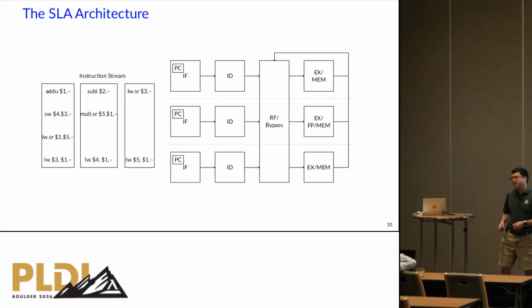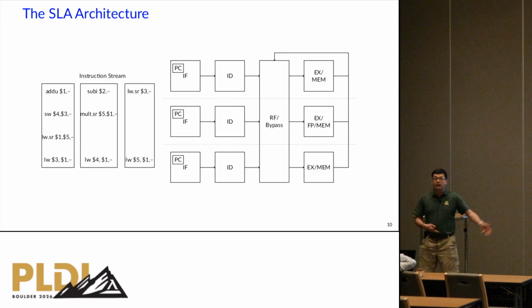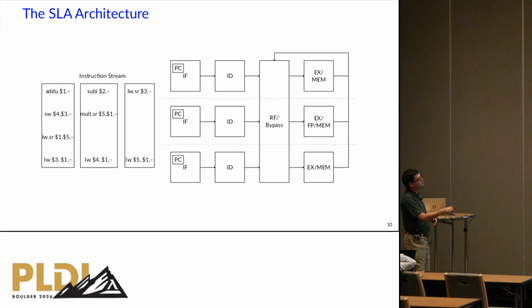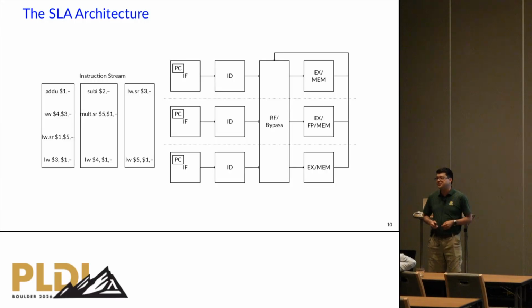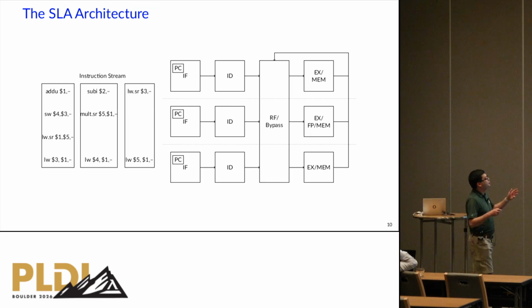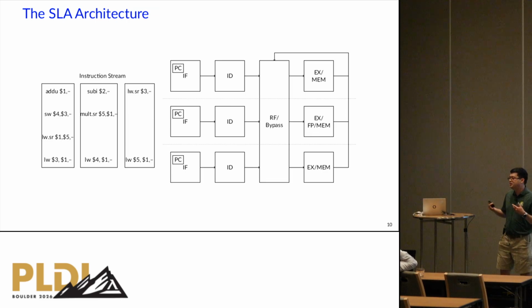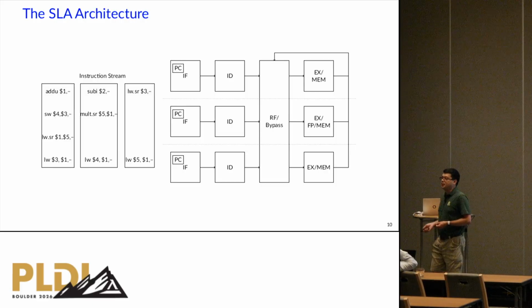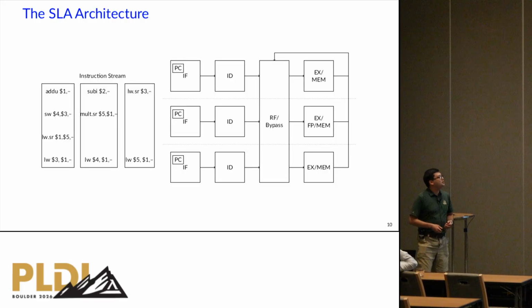So what ends up happening is we end up with a processor that looks like this. It should look very similar to the VLIW processor from before. The only difference is we've broken up the instruction fetch stages so that each individual lane has its own instruction fetch and its own instruction cache. So each cache is smaller, but this allows us to shut off certain lanes when they are not fetching and processing instructions. So this is a big idea.